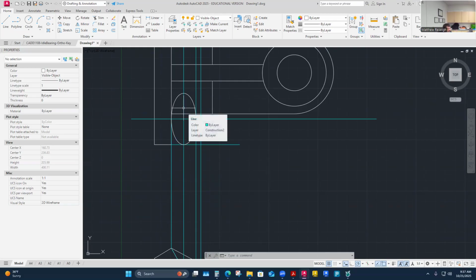Well, now I have to consider what the thickness of that ear is, and it's like 20 millimeters thick, but it doesn't measure 20 millimeters here because it's foreshortened up here. I need to know what the extent of this is from the surface that's towards me to the surface that's buried in my top view.